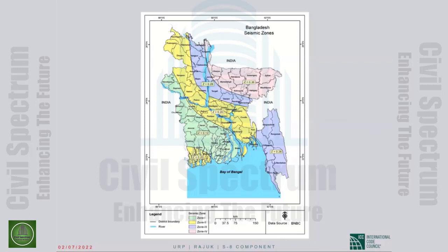Obviously, not all the infill is lost at one time, but even then, in a significant earthquake, the stiffness will go down significantly, and then the building has a different period. It is in a different range of earthquake. So depending upon the earthquake, it now may become more critical for the building or may become less critical. You see what I'm saying?